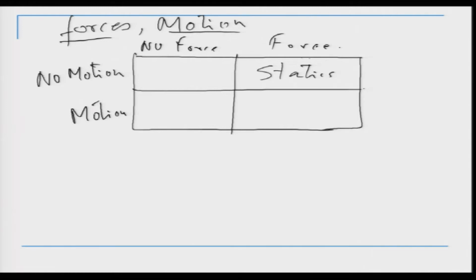Statics is the study of what the various forces acting on the joints are due to an end effector force, when the system is not moving. So it is basically a static system. In terms of the Jacobian we can write this as the joint torques equal to J transpose into F, where F is the end effector forces. This is called the study of statics.